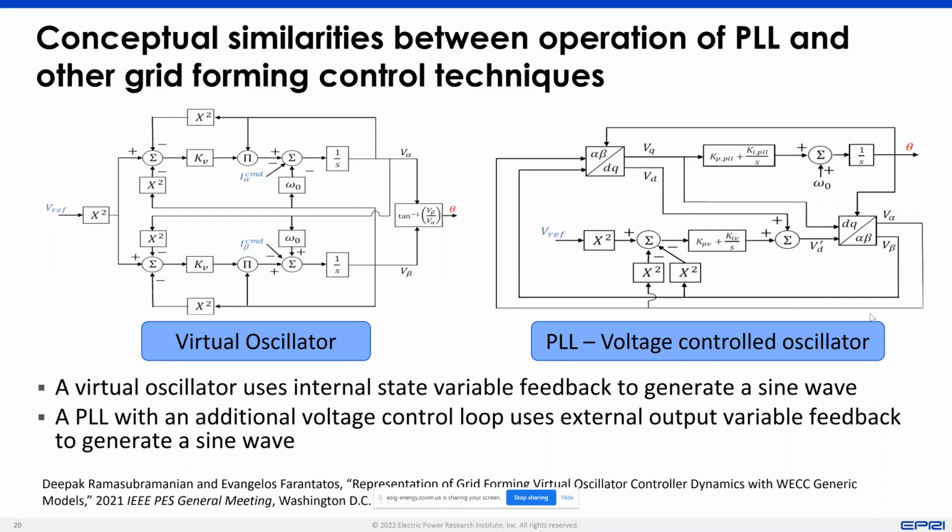It's not linear, and maybe to first approximation, it has effectively a built-in extra gain of 2, if I insist on linearity. Yeah. It strikes me that for large signals, maybe we're asking for yet another mechanism. Oh yeah, for good fault ride-through and so on, there are other things you have to add to this to make it stable for good fault ride-through. Yeah, absolutely.